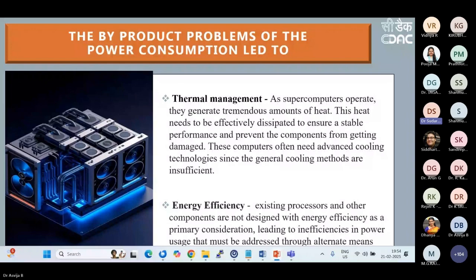For example, today we have a liquid-cooled system, and within that also we have liquid flowing through a pipe like a heat sink, versus the immersion kind of system where the entire hardware is immersed in a liquid, very specialized liquid, which keeps it cool. And then we are now talking about heat sinks that are using new materials, including nanotubes and nanostructures. The packaging itself is done in such a way that the heat dissipation is more, and the hotspots are reduced and more distributed rather than concentrated. So thermal management as a new field for HPC has evolved.